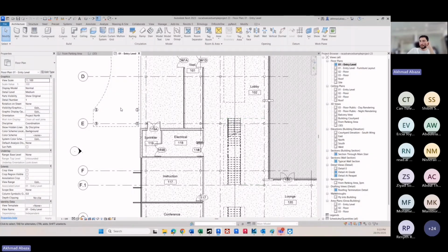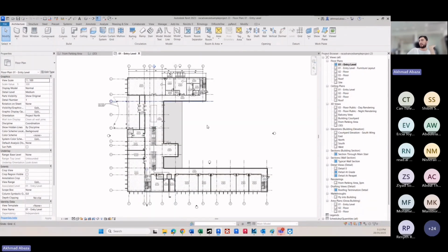There is another trick to zoom to fit, easier than doing the right click and then zoom to fit. We can press the wheel button 2 times. It will take us back to the fit view. I think this is the most practical zoom to fit, which we will use in our daily work.